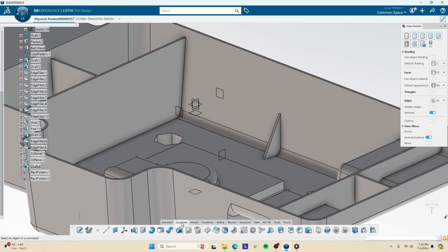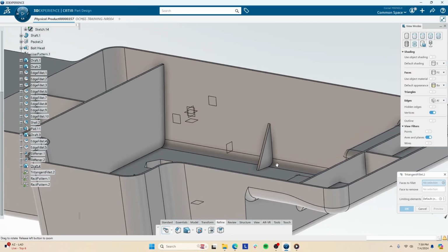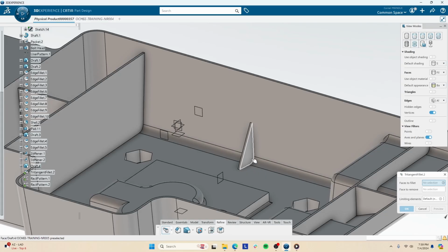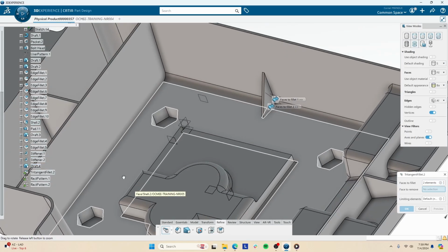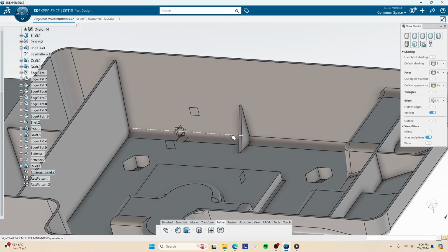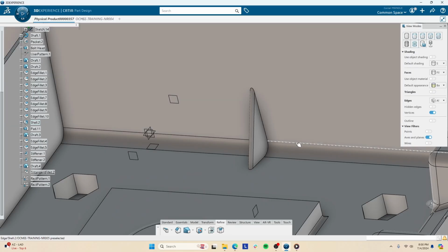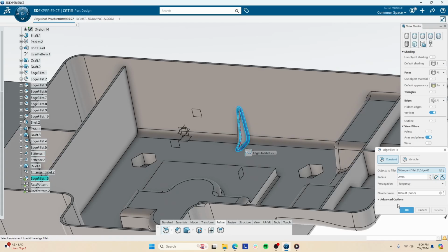And it wants us to do a tritangent fillet, so we go to here, and then on the drop down we click tritangent, and this is where we select 2 of the support faces, and then the third face is where it says face to remove. It will delete that face and then create a tangent surface that connects the 2 faces to fillet. So once I connect that and click preview, you can see that it removes that face and replaces it with a tangent face. And then I could do more of the edge tangents around it.